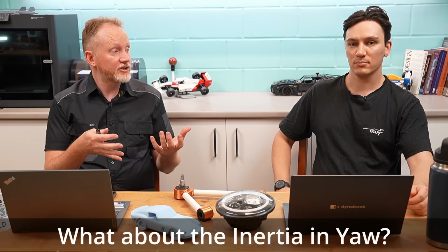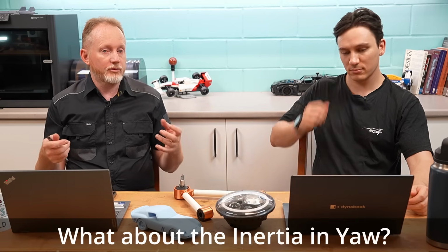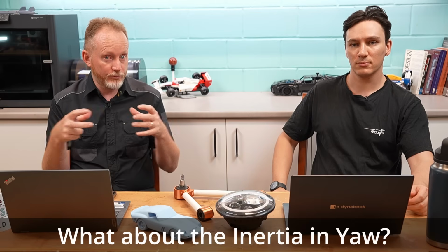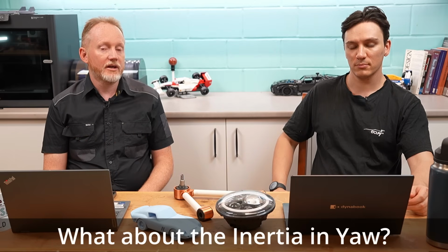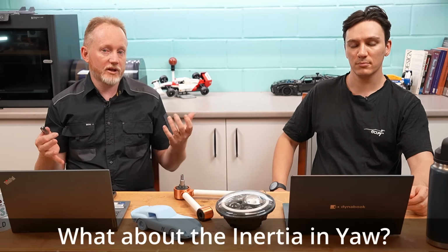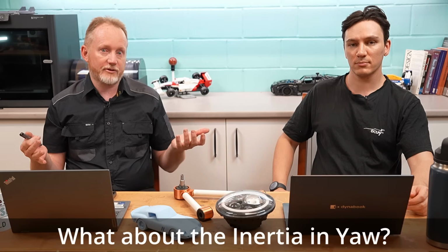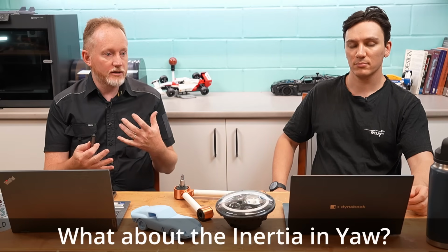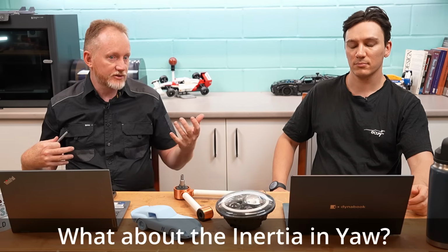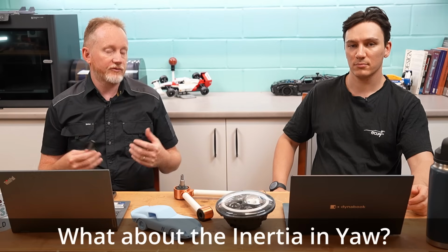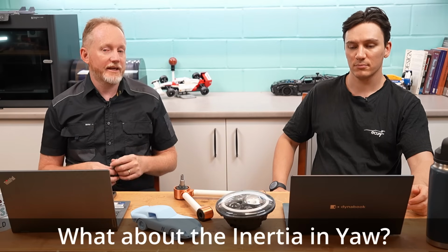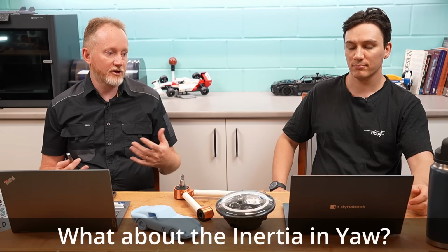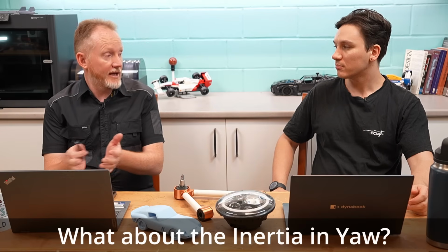If you've gone with a mid-engine car, which is what we've done, you're putting the driver and the engine about as close together as you can. So you've brought those masses really close together. So I think the fact that we're building a mid-engine car means that we're okay with the polar moment of inertia being small. And when you drive a small single-seater race car with the engine right behind you and you feel how rapidly they turn, it gets pretty addictive. You want to have the same sort of thing in a road car, even though you're paying for that instability.